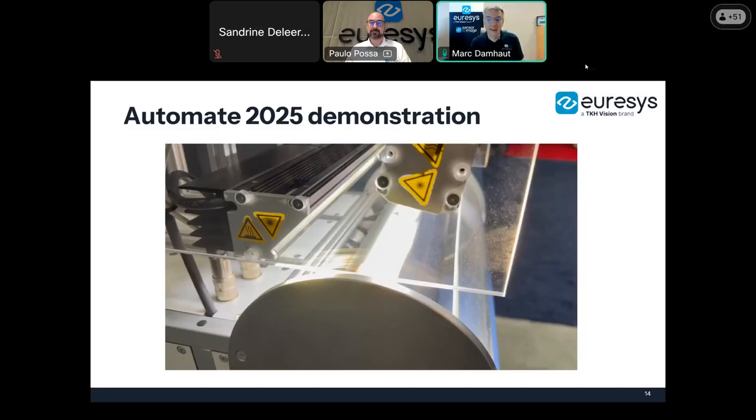And then you can see that it's using two lights for simultaneous interleaved dark field and bright field illumination. So the bright field illumination is vertical, and I'll try to show you on the image. If you see my pointer, that's the bright field light, which is almost parallel to the camera axis. And then we have the dark field illumination on the left with a much lower angle.